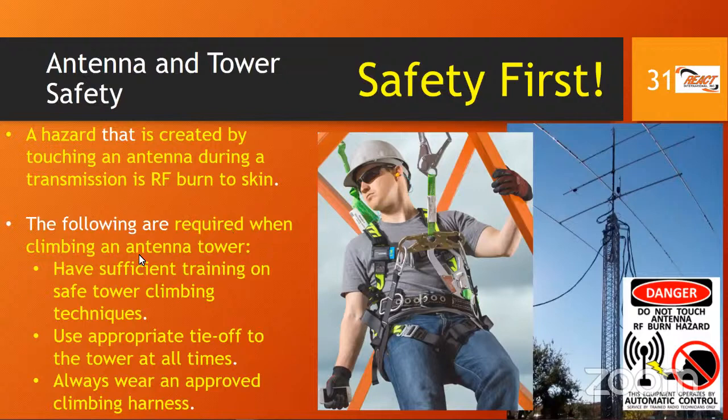So the following are required when climbing an antenna tower. First off, you have to have sufficient training on safety tower climbing techniques. So don't just think, hey, I've seen someone climb a tower, let me go try it. Be very careful. You need to be trained. You need to be aware of all of the safety precautions before you think about climbing a tower. So that's the first point.